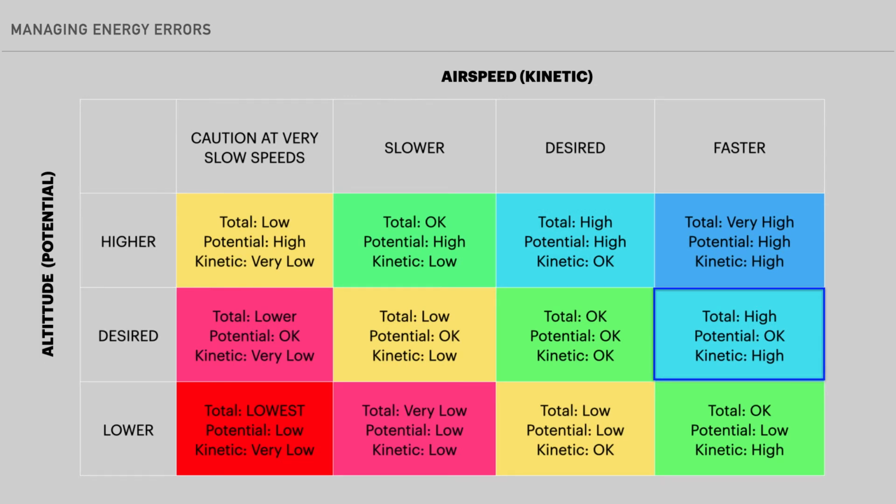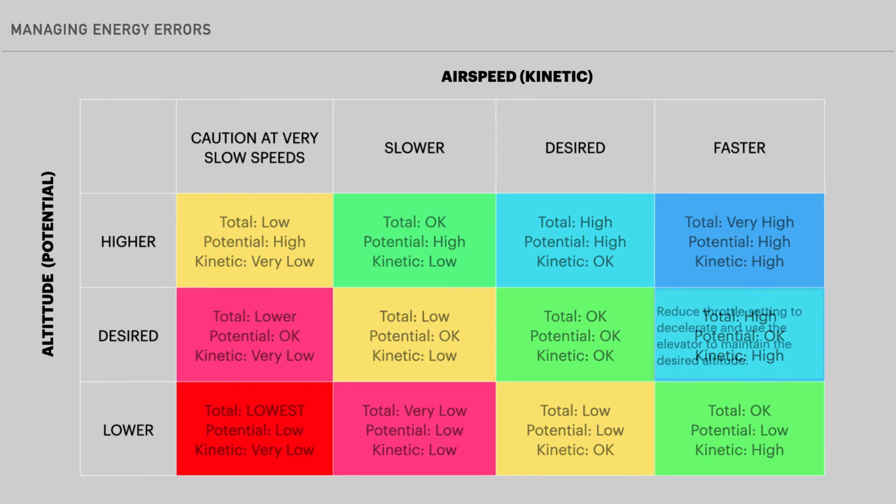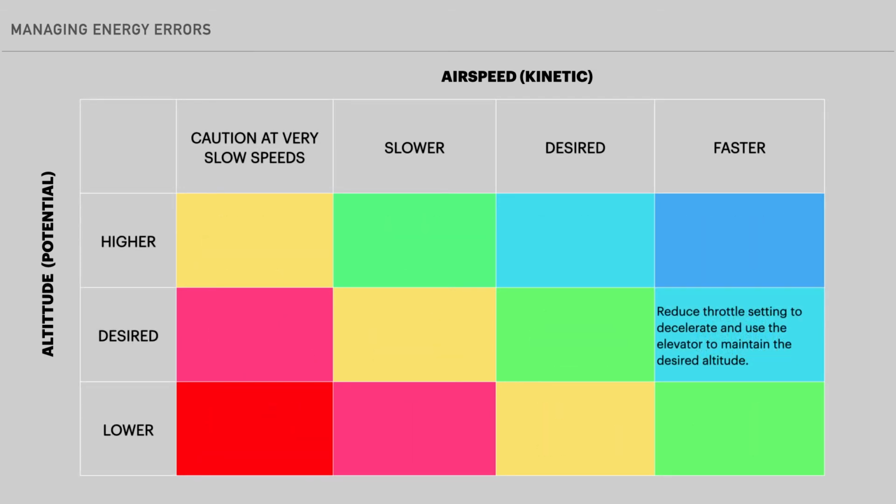Imagine flying along when significant turbulence is encountered. The pilot would like to decelerate to maneuvering airspeed to avoid overstressing the airplane. The altitude is on target, but the airspeed is higher than suitable for this flight condition. The correct response would be to reduce power and apply appropriate elevator back pressure to maintain level flight as the aircraft slows to the desired airspeed. By reducing power, the total energy decreases to allow aerodynamic drag to slow the airplane. Upon reaching the new desired energy state, adjust pitch attitude and throttle setting as needed to maintain the new path speed profile.